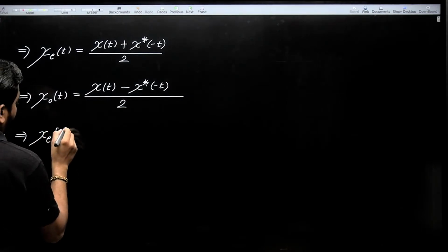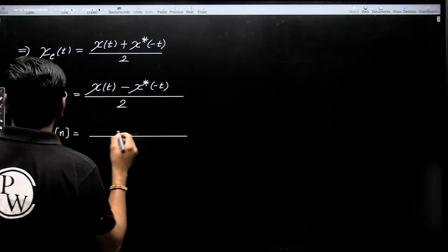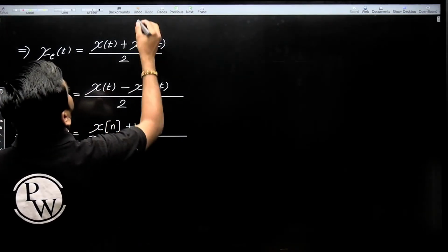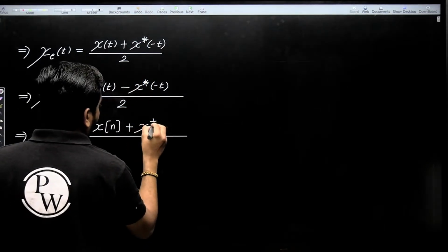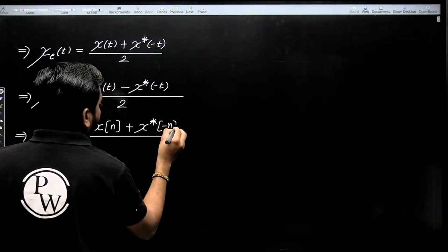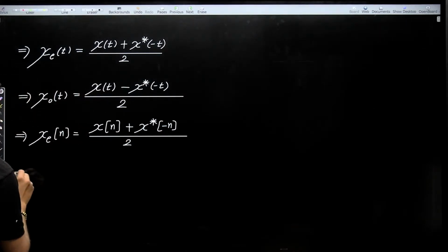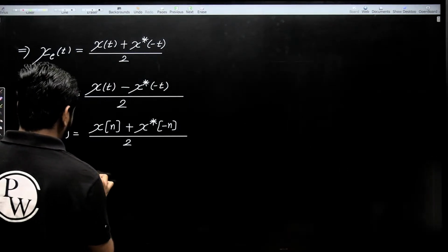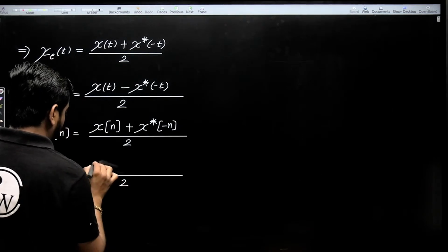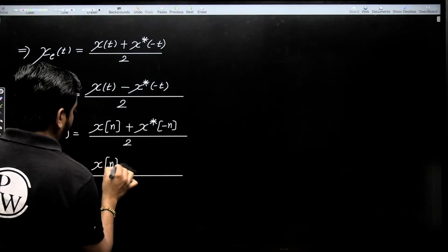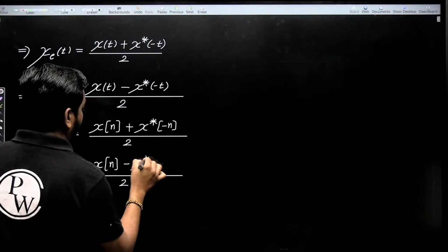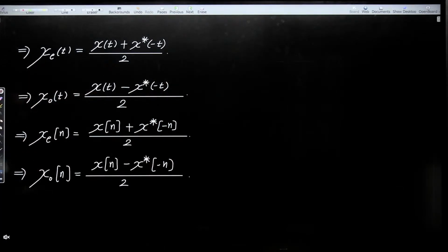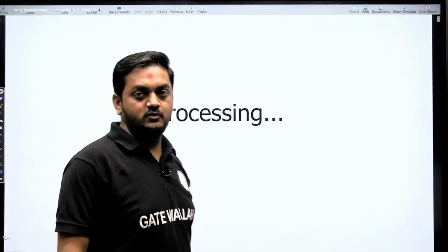Xe of n is equal to x of n plus x conjugate of minus n, whole divided by 2, and its odd part is given by x of n minus x conjugate of minus n, whole divided by 2. Fine. Okay, now let us solve some questions based on this topic.